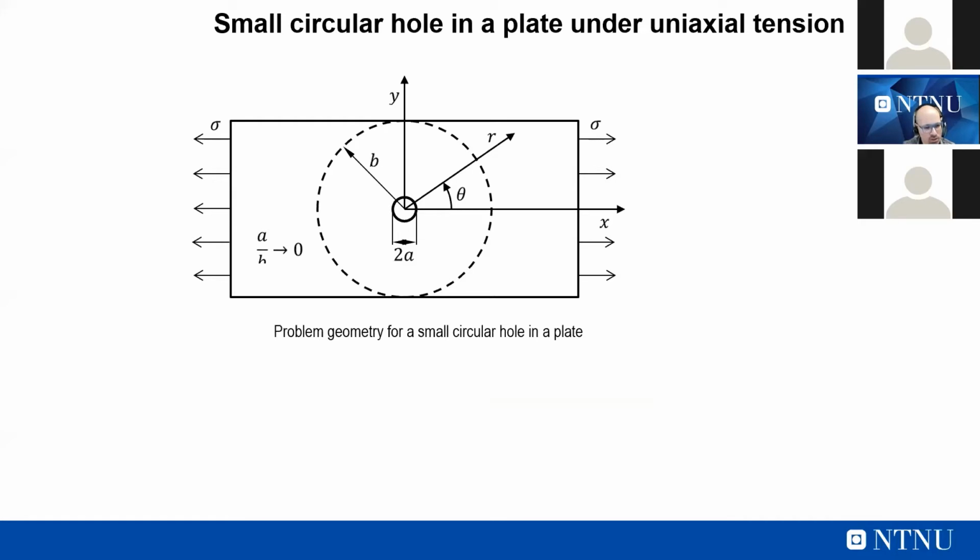This case you have probably seen many times in your books. But it is important because this is the first available solution where we have a closed form solution for studying the problem of a notch. And of course, you can think of this circular notch also, for example, as a defect in your component. It is not only a notch, it can also be considered a defect inside the material, and you can use the same framework of equations for studying this kind of defect.